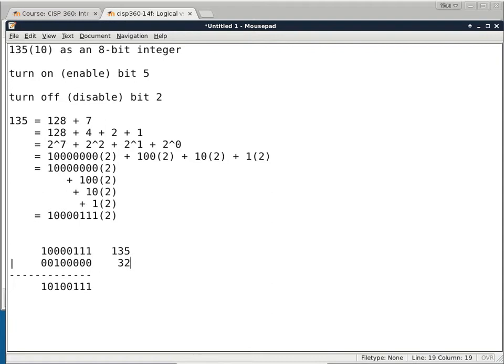Where did the bottom one come from? The 001000. You mean here? The one before that. You mean this one? Yes. This is the bit pattern that we need to specify to perform the bitwise OR to turn on bit 5, to change bit 5 to a 1.